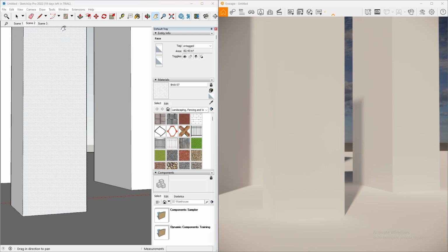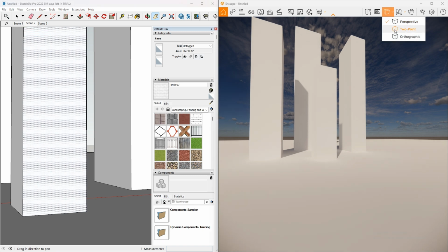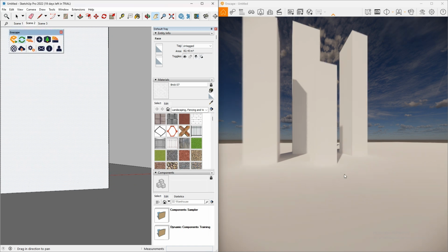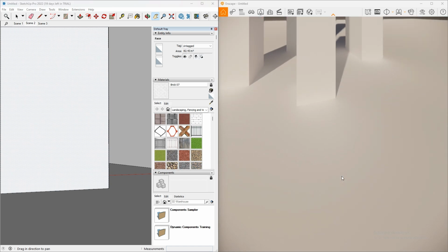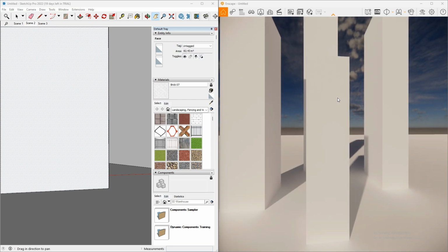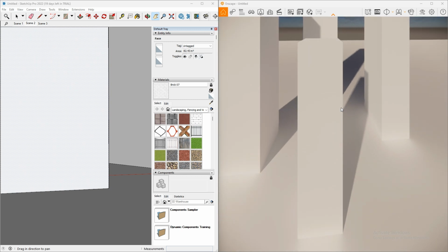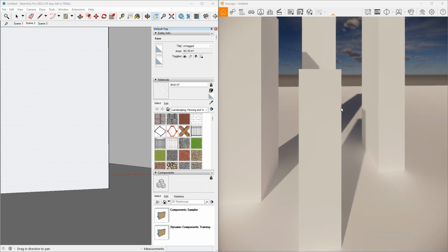So if you wanted to mitigate that, you can change it to 2-point perspective, which automatically locks in the vertical lines of your screen to make them 100% straight. However, the downside is that the second you start to move either too far down or too far up, it drastically warps your model to unrealistic proportions because it's trying to match that vertical nature of your screen.